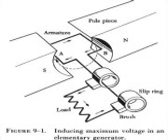These coils are mounted on the same poles on which the shunt field coils are mounted and, therefore, contribute a magnetomotive force. Figure 9-17: compound wound generator, showing series field coil, shunt field coil, and load.